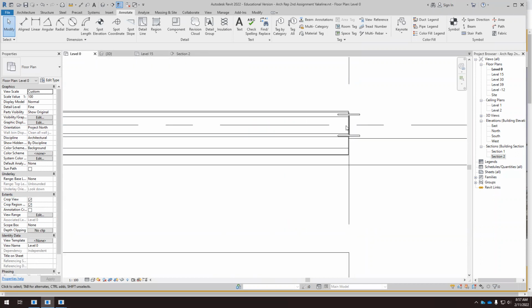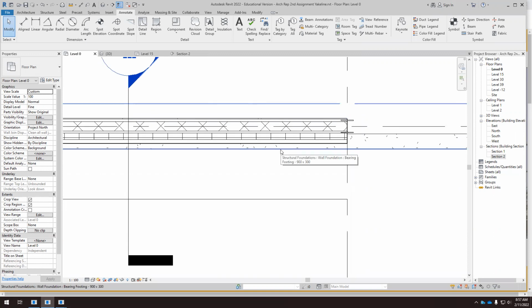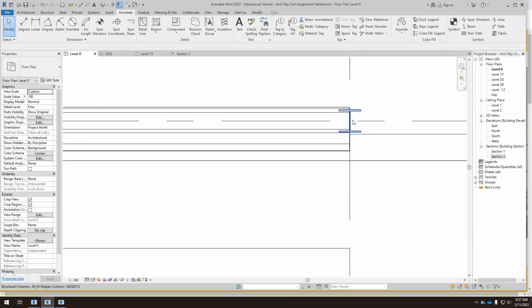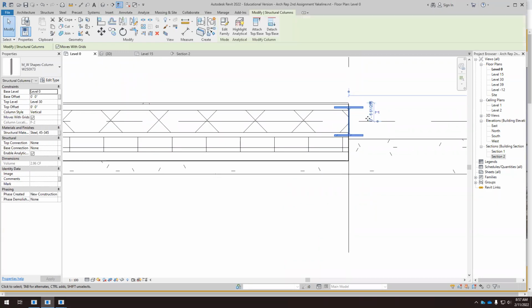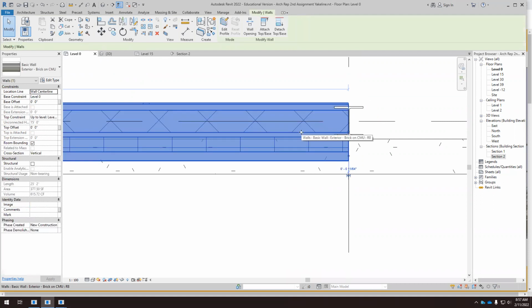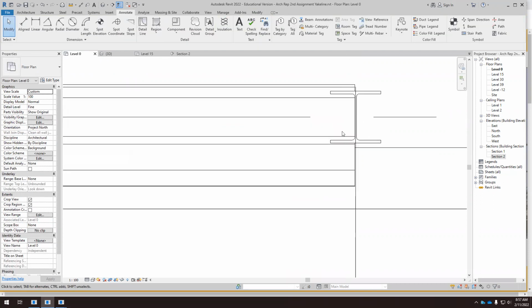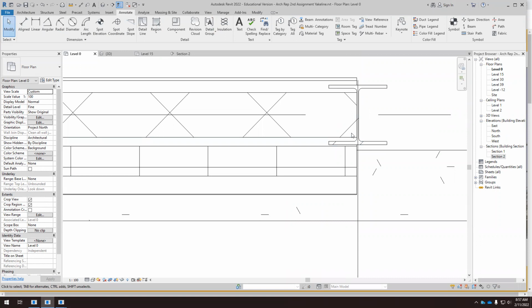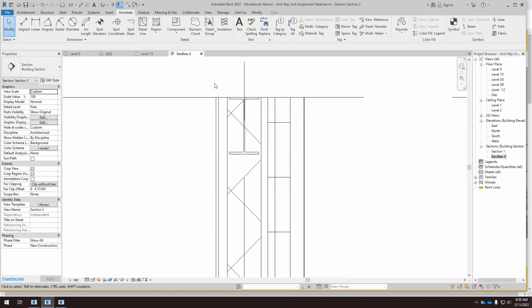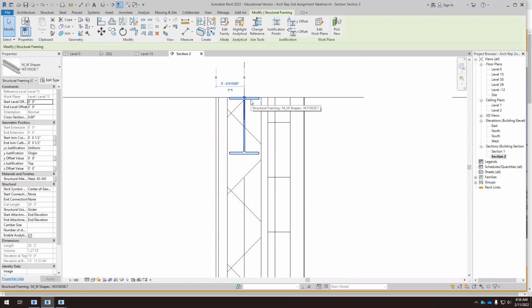So that's it. I'm not just placing the wall and that's it. No, I'm thinking about construction now. If I'm dealing with different materials, like a steel structure and a concrete masonry unit wall, I have to make sure that this connection is good and I don't interrupt the thermal insulation because I don't want a thermal breach here. And this is the most important thing: the thermal insulation goes through, it's not interrupted by the steel column in plan, and it's not interrupted by the steel beam in the section.